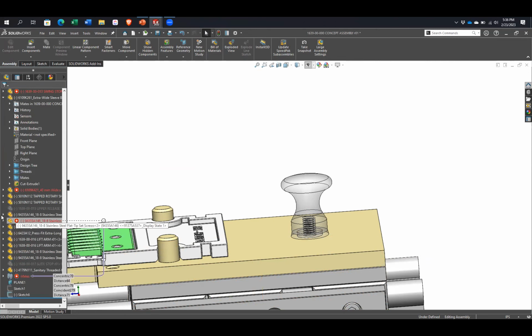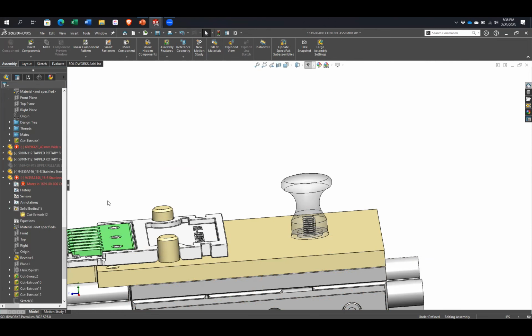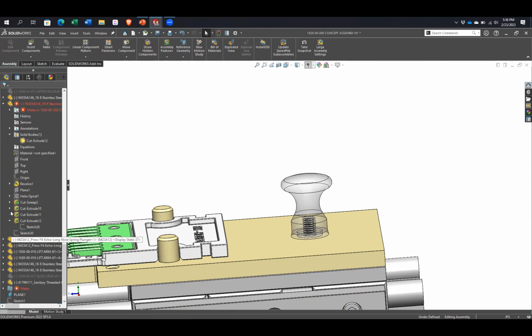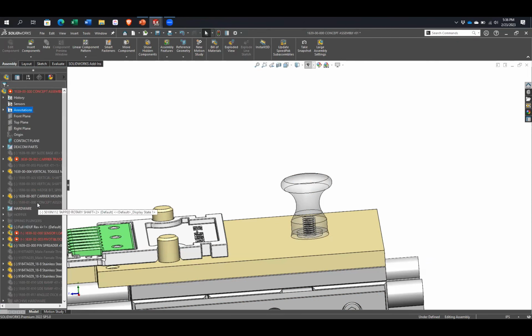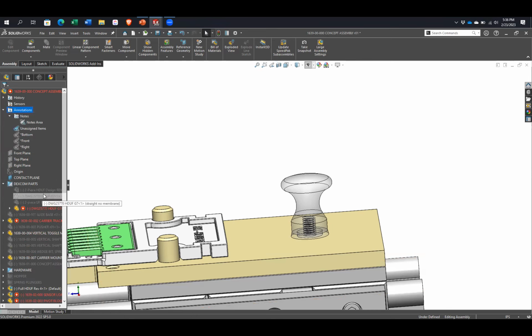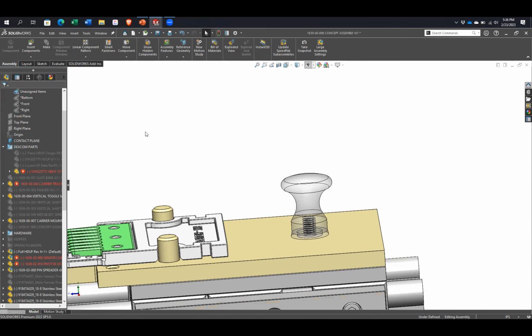So you probably all know if you open a lot of things, sometimes your feature tree can get kind of crazy and you've got a million features and you just want to collapse. I always do this anyway. I right click and hit collapse all so I can get a nice clean feature tree again. But sometimes you want the inverse and there's no expand all option. So eventually he figured out if you press the star key while you click open, it will actually open.